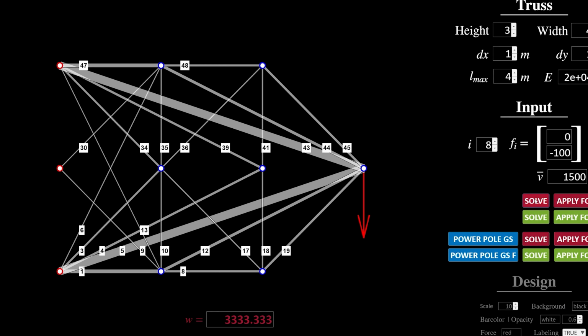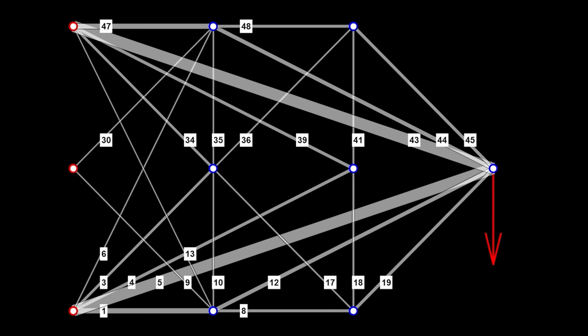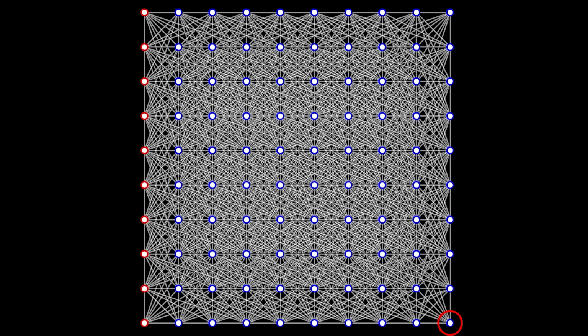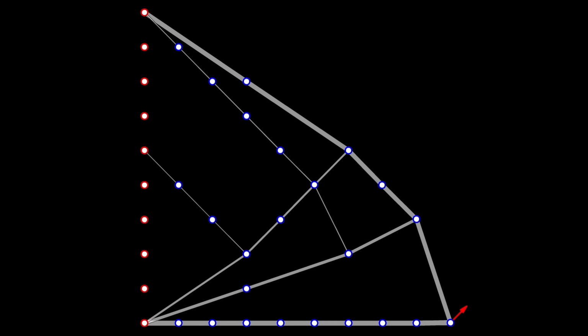And I'm pretty sure that you would agree that this solution does not look that obvious. Well, now imagine optimizing a 10x10 truss with over 1000 bars. The node bar matrix B for this truss is a 180 times 1106 matrix. A matrix with nearly 200,000 elements. While this might sound incredibly large at first, it's not considered a problem for an SDP solver. In fact, we obtain a solution here in less than a second. In my opinion, this is quite fascinating.